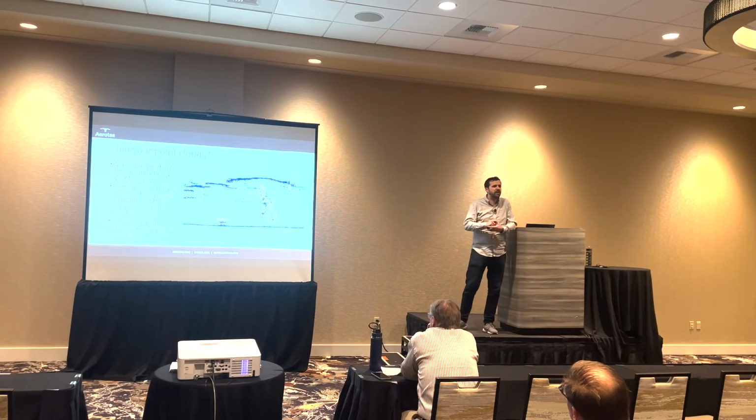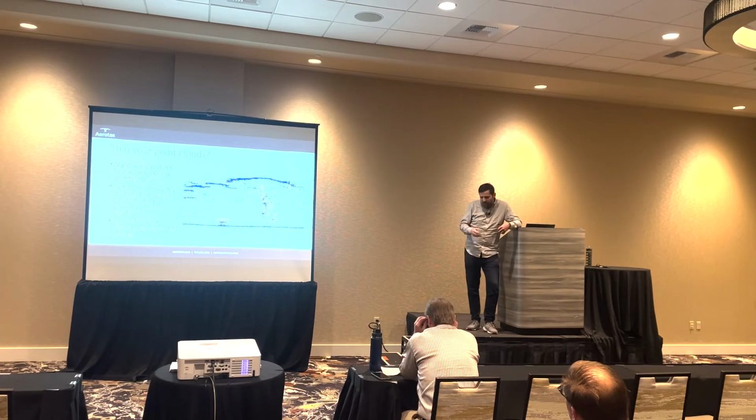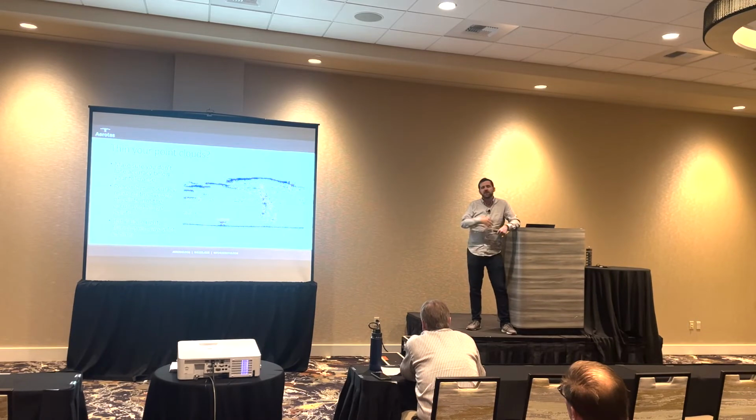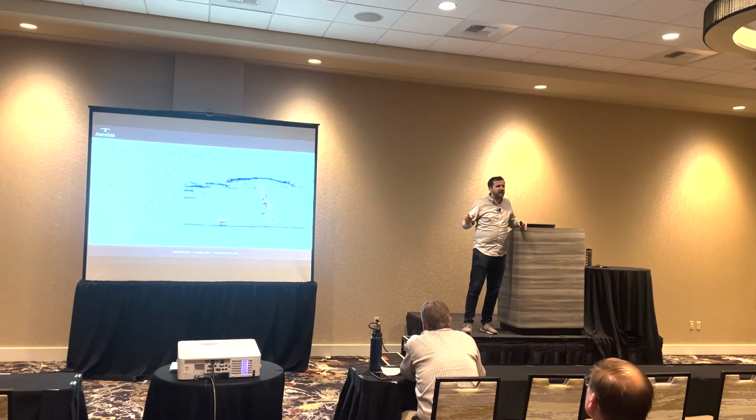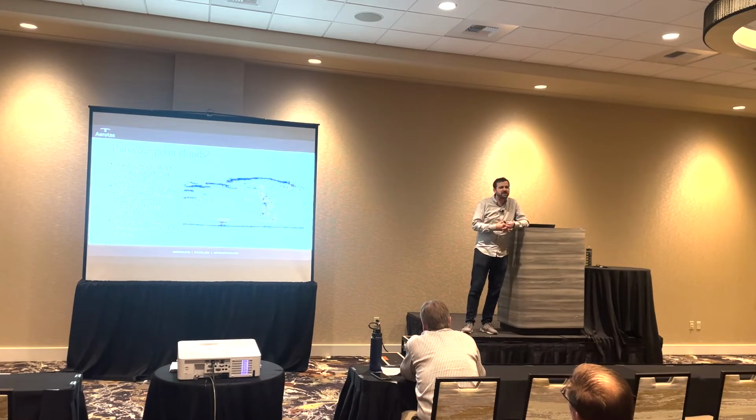Thinning the point cloud, by the way, there are different methodologies to do it, right? The first methodology is one that we call dumb decimation, which is you basically take a point cloud and you just delete every other point. Or maybe you delete 9 out of 10 points. That's just randomly deleting points to thin it down, make it smaller.